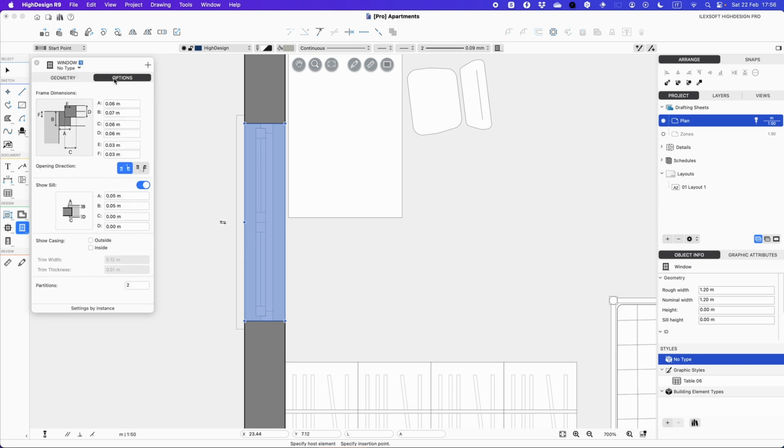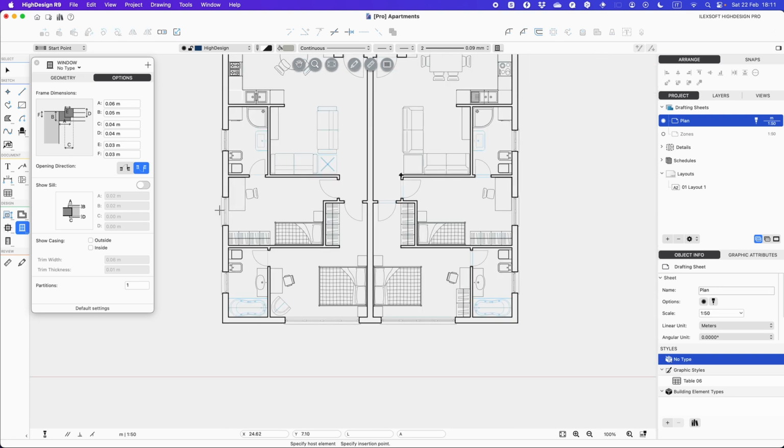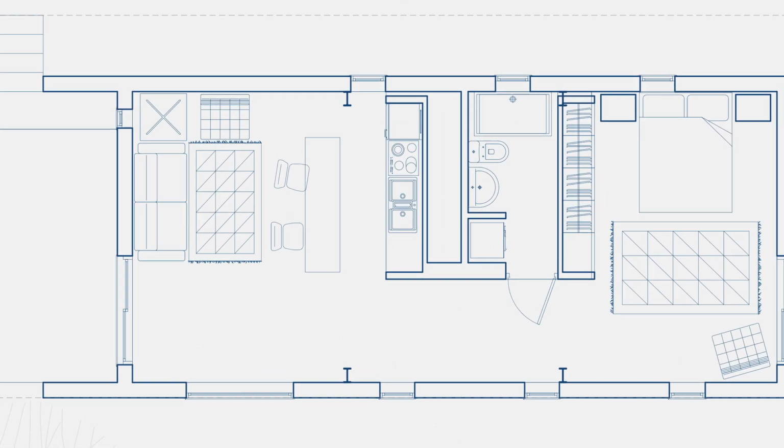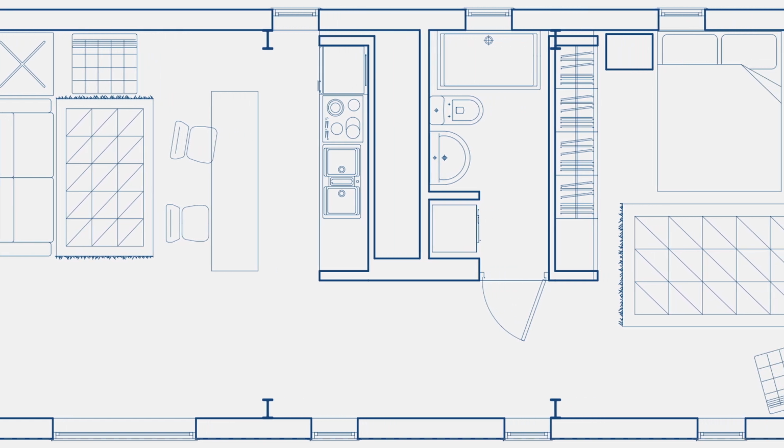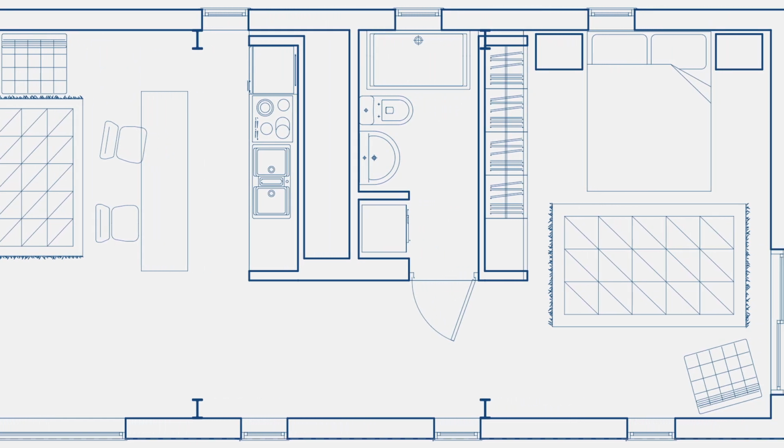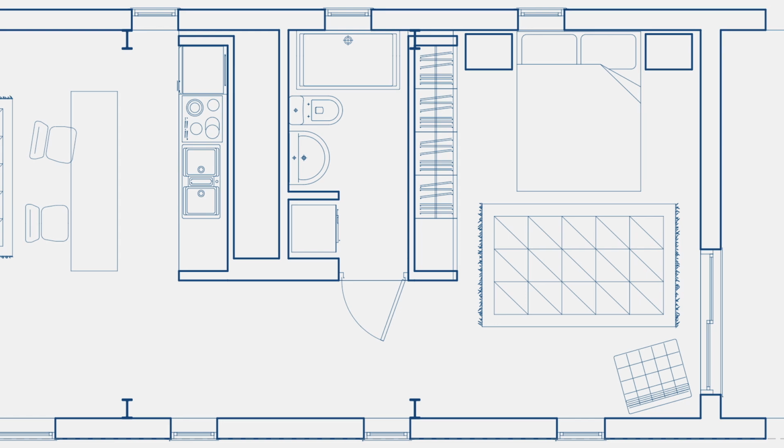They are also hosted elements. Doors and windows can only be inserted in a wall, which is their host element. Because doors and windows are openings in a wall and share many common parameters, the method of insertion and editing is basically the same for both elements.